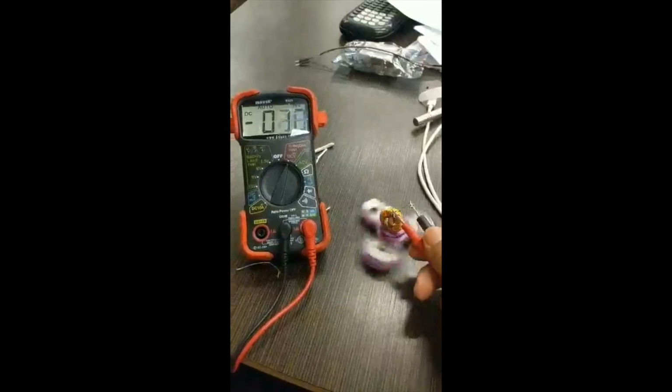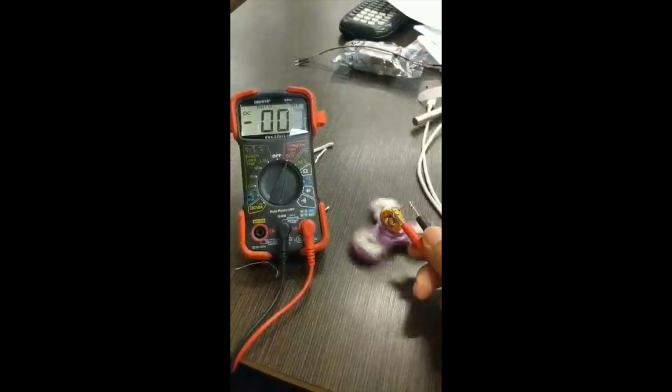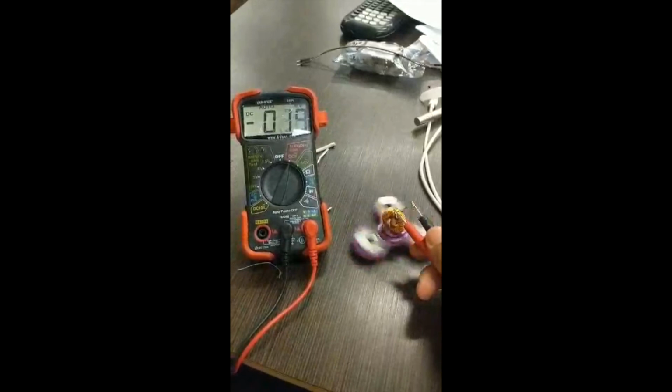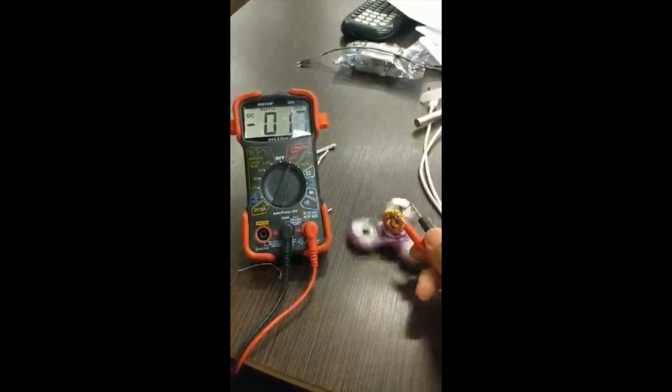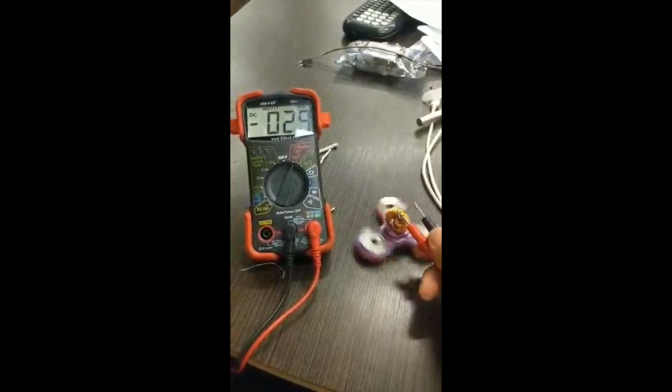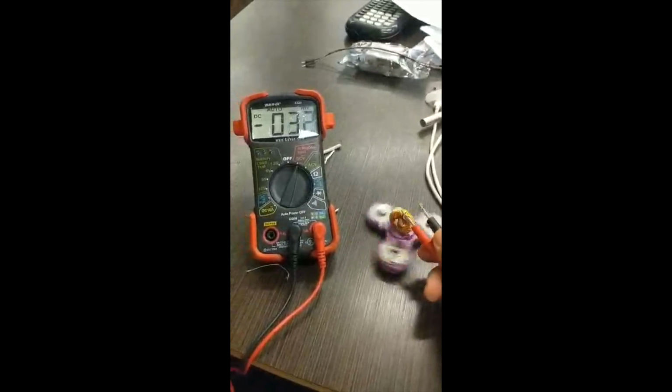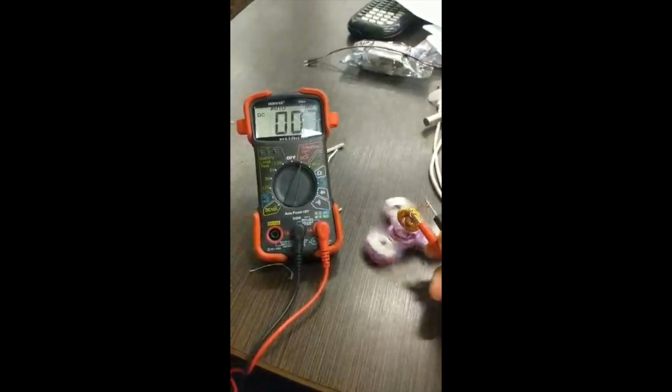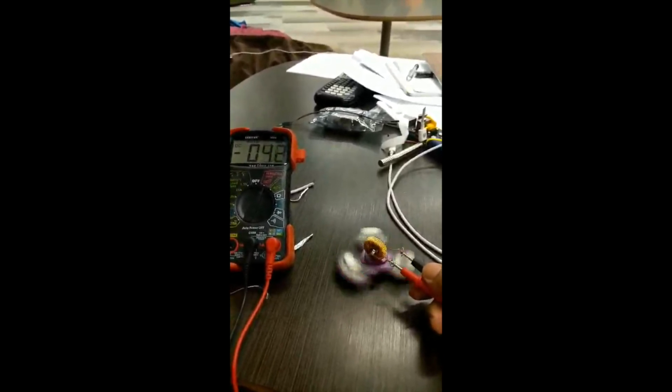Here you can see a coil inductor generating voltage as it is lowered between the magnets. The magnets are on the outer bearings of the spinner and rotate around the inductor, generating a magnetic field. In order for electricity to be generated from the mechanical movement of the spinner, the field lines must be perpendicular with one another. As seen from the video, the peak voltage generated from the movement is around 4 millivolts. Unfortunately, this value is too low to power a phone. However, if an inductor with more coil turns and stronger magnets were used, a greater field and resulting electrical power would be generated, which would allow a smart device to be successfully charged.